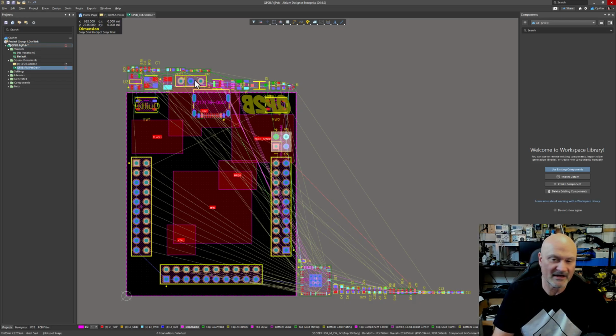I also have this other connector up here, which is for the single wire debug. It is not critical, so it's left outside the board with all the other components to allow Quilter to do the placement for that and optimize that.